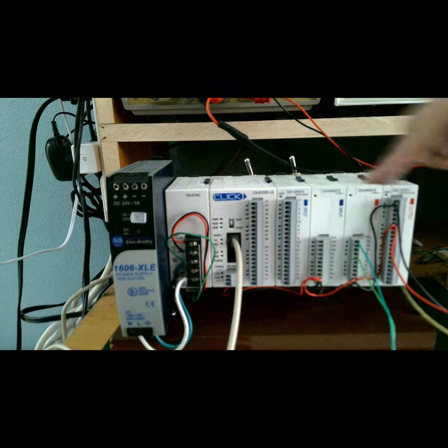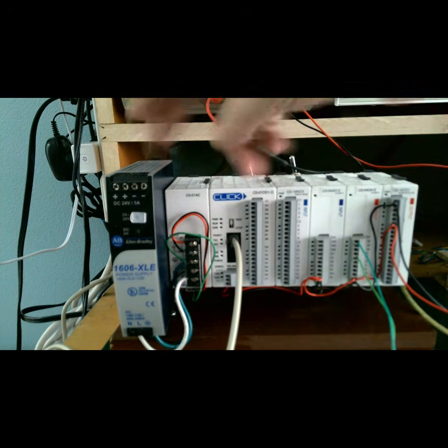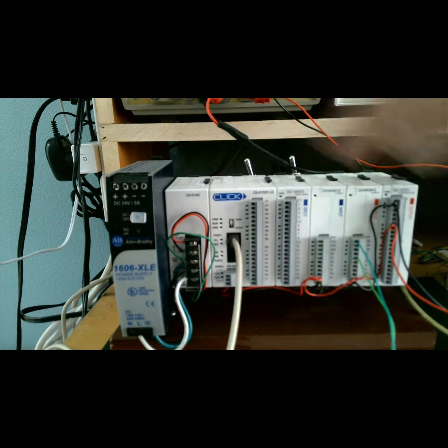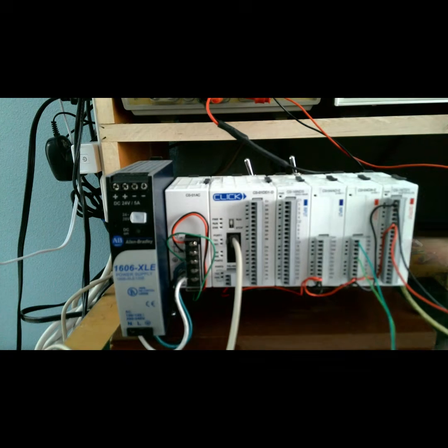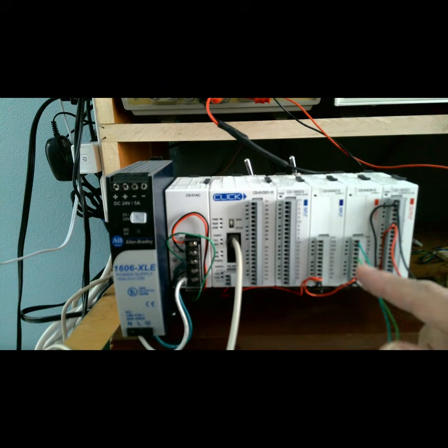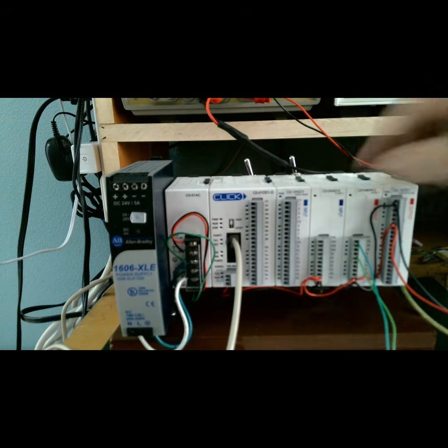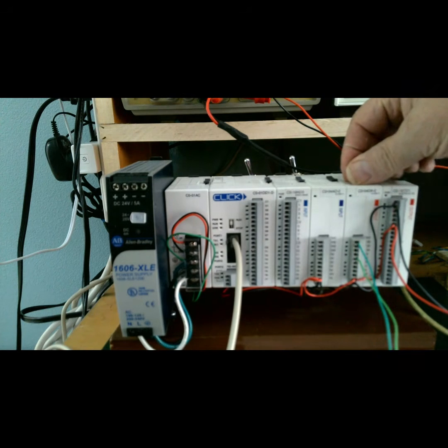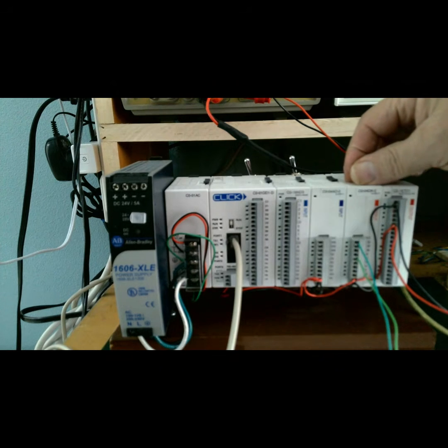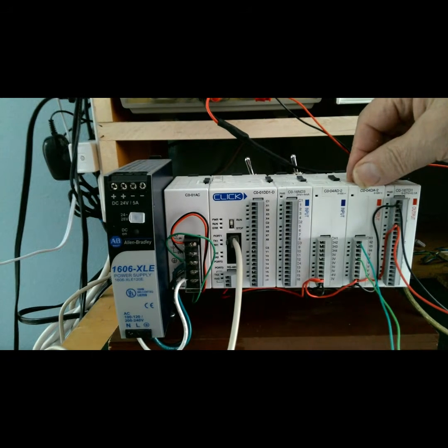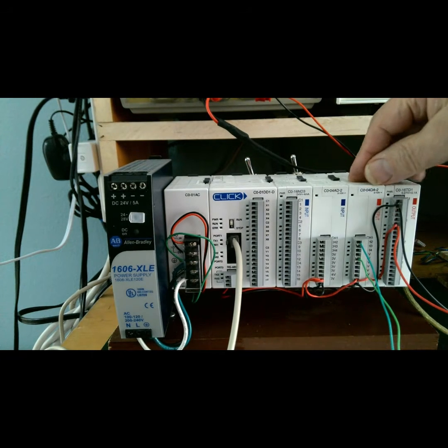This is a programmable controller with an external power supply that I use for other stuff. This right here is a digital to analog module, meaning that I can input a number and get out a corresponding voltage. Now, this particular one is a 12-bit module, so with a little bit of math, the next job is going to be to convert our voltages into an equivalent binary number.